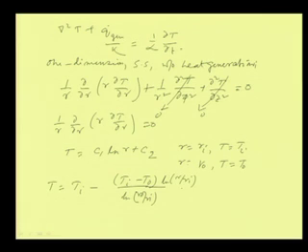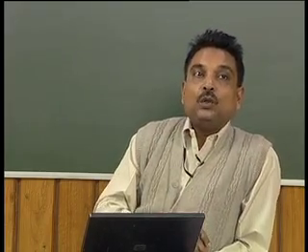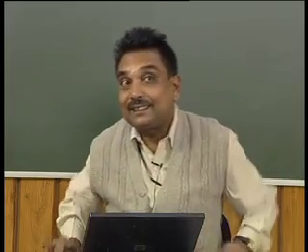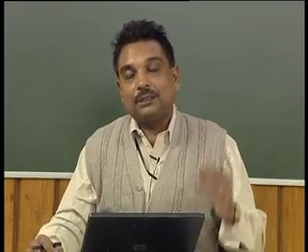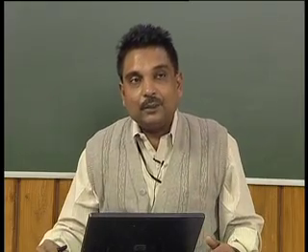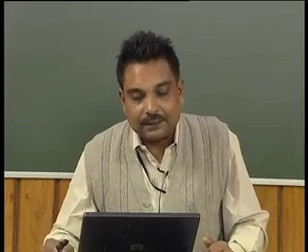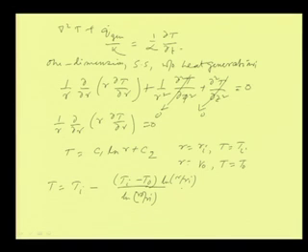So, now one thing is understood that in case of heat transfer through a plane wall, we found that temperature is a linear function of the coordinate when there is no heat generation term. But in case of cylindrical coordinates, temperature is not a linear function of the coordinate, and the major reason is that as we move in the r direction, the area is continuously changing. So, we are finding that temperature is a nonlinear, logarithmic function of the coordinate.